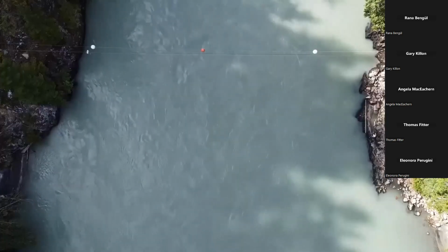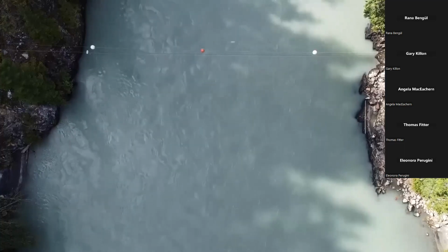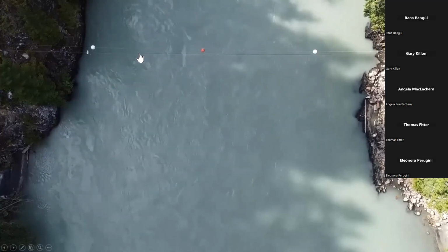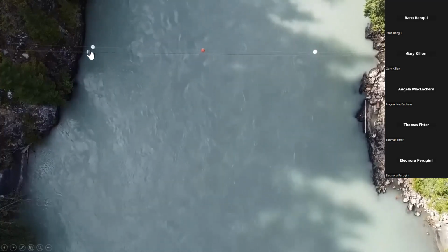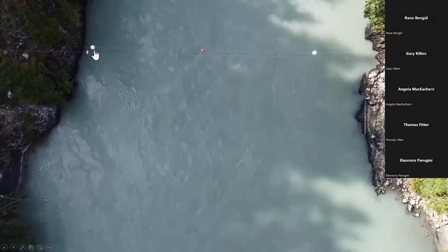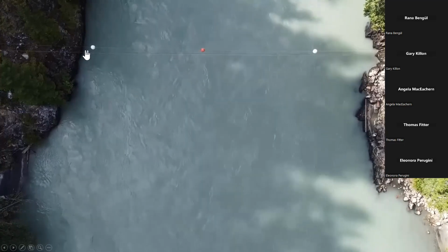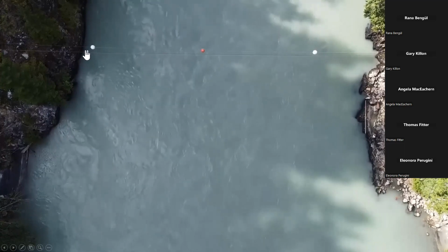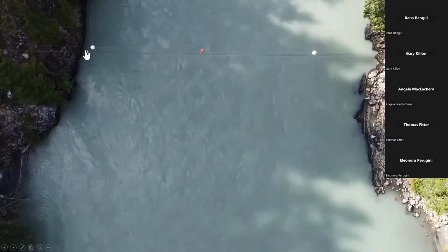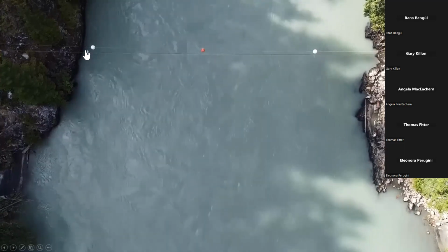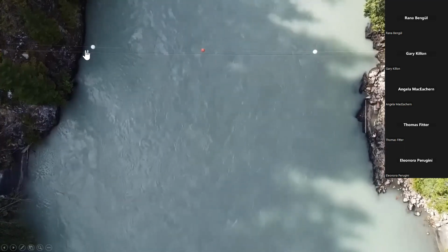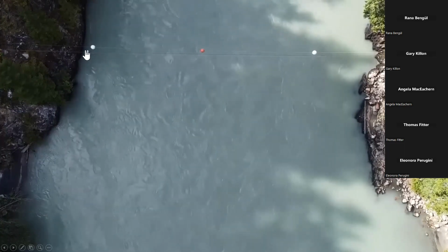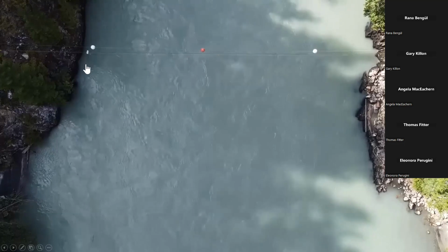So now I'll go into some examples. This is a site in BC. You can actually see that there's a cableway going across, and there's an RP30 surface velocity radar on here as well. A lot of cableways have been decommissioned across the country for safety reasons. There just wasn't enough maintenance. And so in a number of sites where we used to be able to measure discharge from the cableway, that's no longer an option. And so drone videos have a lot of potential to fill in that gap.